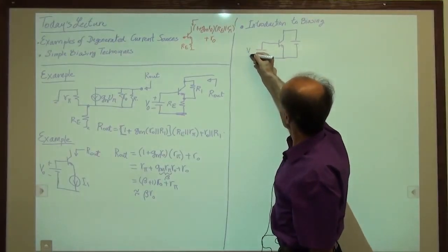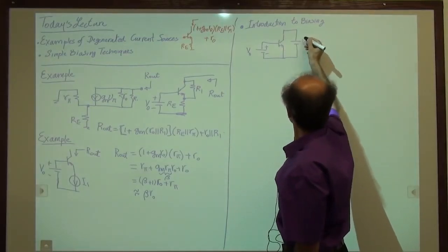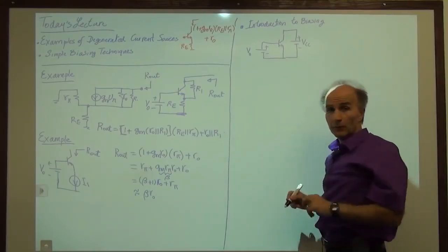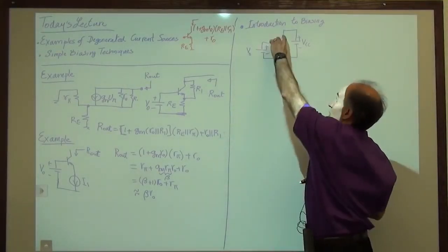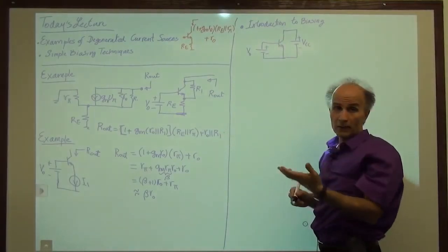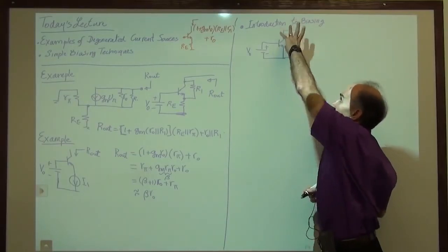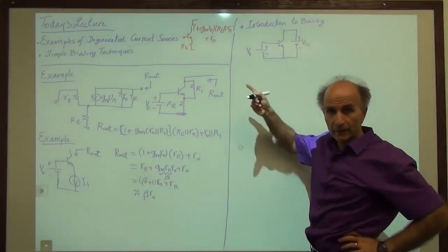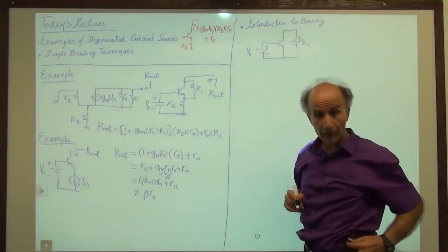This doesn't have any name, it's called a V0. Sometimes this has a name, we call it VCC. Doesn't really matter. The idea was that this junction is forward biased by a reasonable amount, maybe 800 millivolts, and this junction is reverse biased or at least has a zero bias across it. So this VCC has to be high enough. Of course, we have some resistors, etc. around. We're not showing those here.